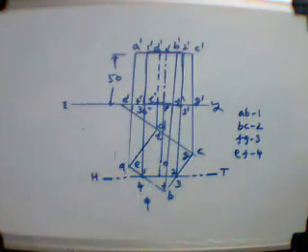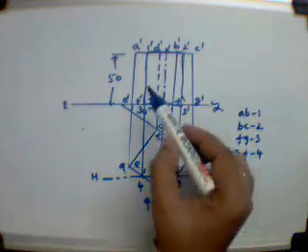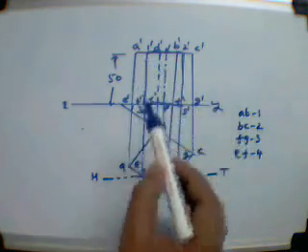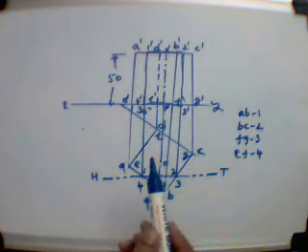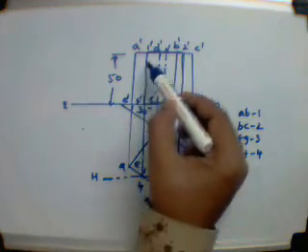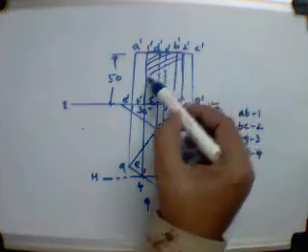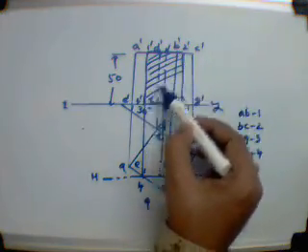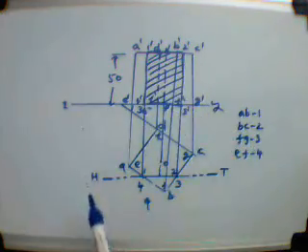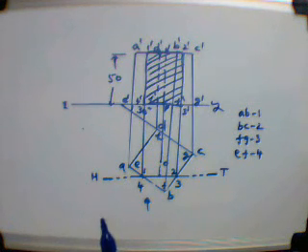This is the section. So we have to represent the section with hatching. Hatching means 45-degree uniformly spaced lines. So draw the hatched lines, 45-degree uniformly spaced lines. Then we have represented the front view.